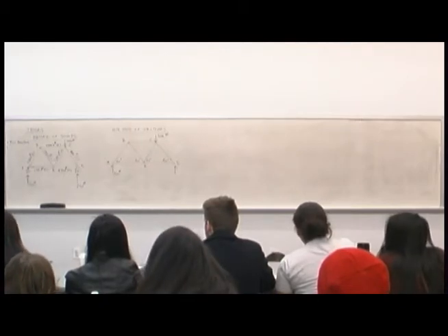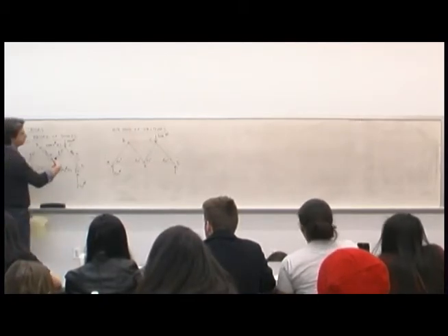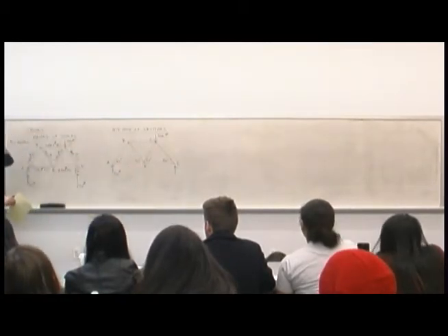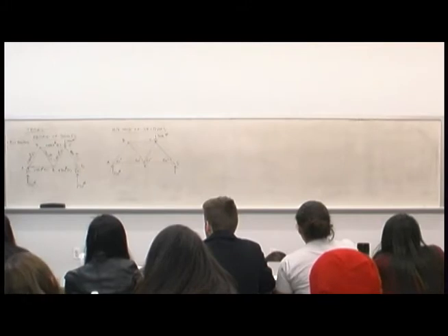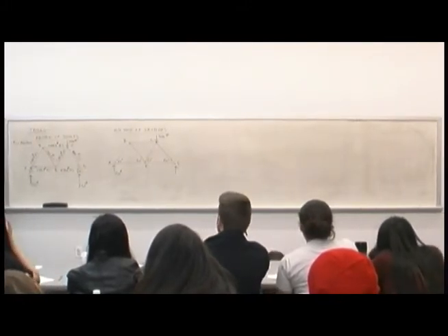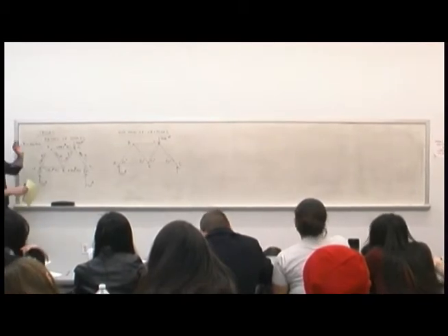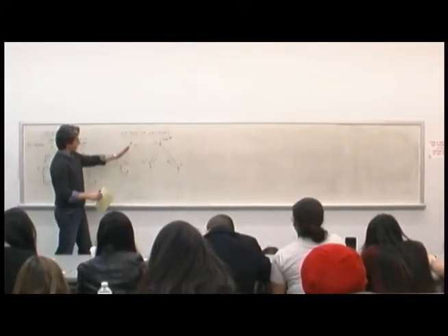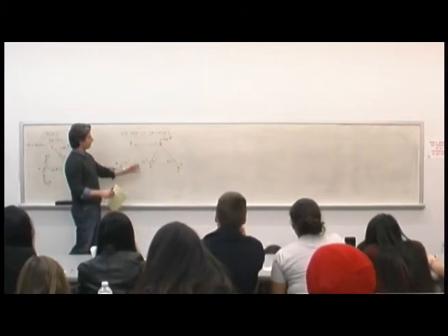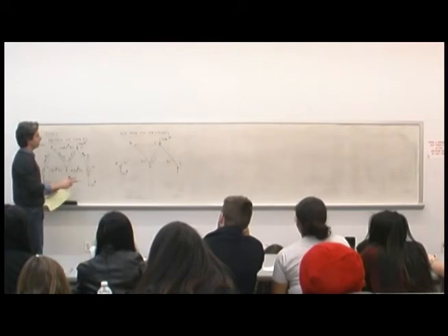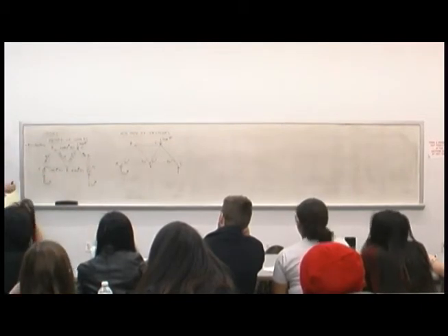So now this is a technique called method of sections, and to a certain degree we've done this also, maybe not as explicit, but we've done a method of sections type analysis before. What we want to do is take apart the truss and look at the forces internally, and balance it in equilibrium again.